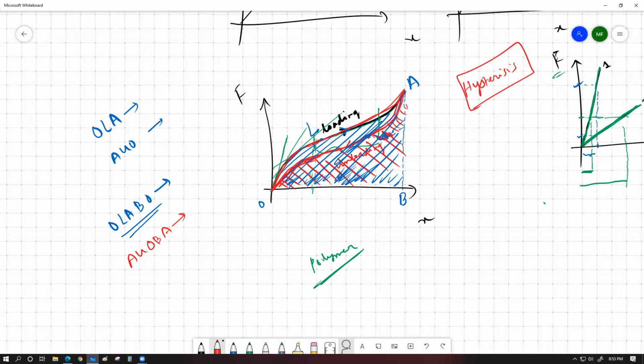while unloading. So during loading it takes in more energy, but during unloading it gives out less energy. But ultimately our dimension is achieved exactly the same. That means in one cycle, meaning the process of deforming it once and then getting back to the original dimension once. This is one cycle. In one cycle, this specimen is going to store this slice area amount of energy within itself.